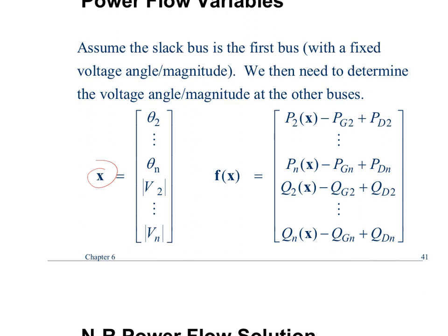Now you will note theta 2 does not need to be theta 3. Do you agree with that? It only is going to be theta 3 if you have to write a power balance equation at that bus to solve for theta 3. So if bus 3 is a slack bus, for example, you wouldn't have a theta 3.